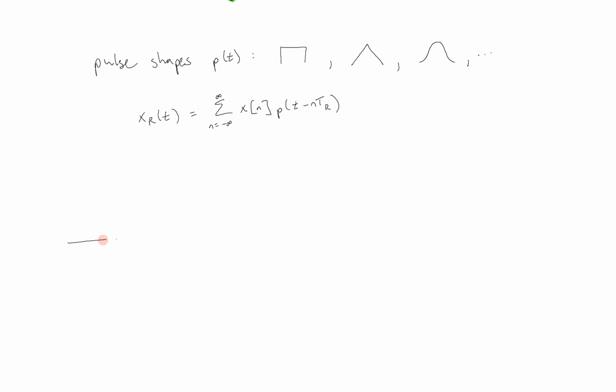So specifically, let's say that we have a continuous time signal that we sample, and this is at some sample rate corresponding to a sampling period of t sub s. And now, after we do this, all we have left are sample numbers. Sample number 1, 2, 3, 4, and so on. We don't really know anything about the time in between these samples unless we also know the sample rate. If all we have is a series of samples, all we know is their sample number. So therefore, the spacing between them is technically arbitrary.